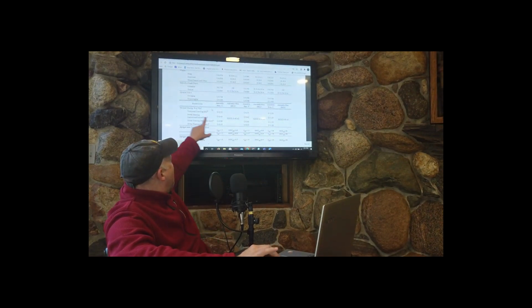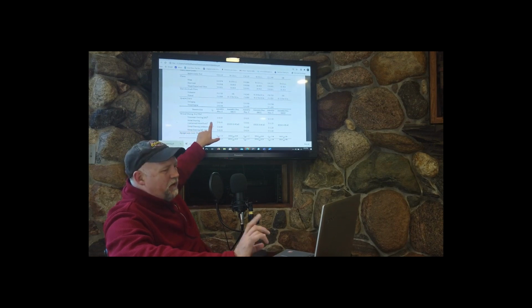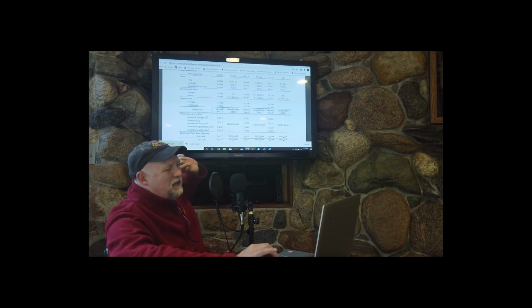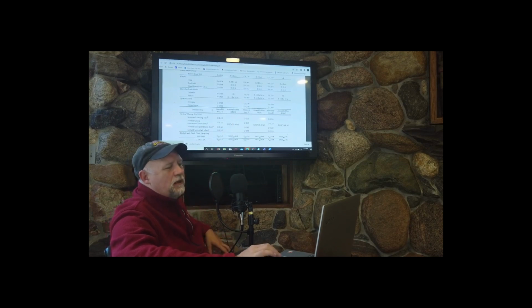All right, so let's check out some of the U values. Metal framing, curtain wall, storefront, that's a lot of the windows that you're going to see in commercial buildings. Has a U value of 0.45 as a minimum. And this SHGC, there is a conversion factor between this and a shading coefficient. I'll give you that conversion factor. I think it's in the notes in a little bit.